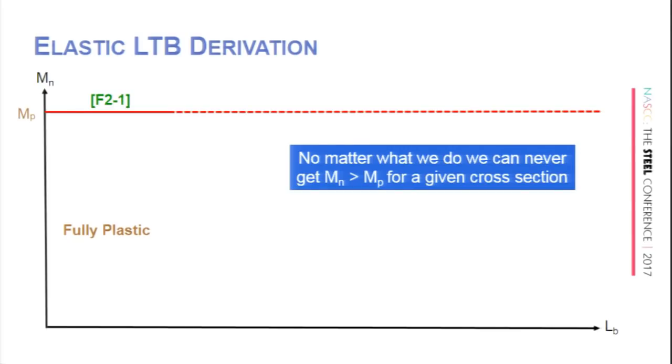I did one test when I was teaching at the University of Florida. I was there for a few years. And I had a student, we were testing a roof for uplift. And how was I going to do the test? Well, we built this nice roof. It was wood trusses, everything was scale. And I said, do not do the test. I was going away, coming back, and then we do the test. We were going to turn the roof over. We wanted to do a uniform uplift, but the simplest way, we figured, since we had plenty of sand in Florida, was to load it with sand. And he did the test before I got back. And guess where the test was when I got back to the lab? On the floor. Because once something's going wrong, you can't recover unless you stop and quickly remove some of that load. So more times than not, we do things very safely under a displacement control situation.